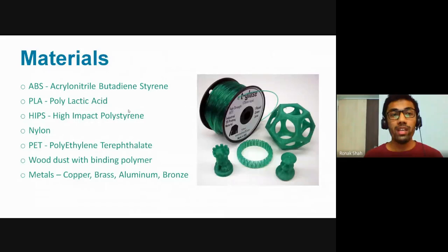This is one of the most favorite materials for all the industries, for developing prototypes or for hobbyist 3D printing jobs, because of all these reasons. But the disadvantage of using ABS is that it is not eco-friendly. And secondly, during the printing process at this glass transition temperature, it generates a lot of fumes, and these fumes are dangerous for humans.